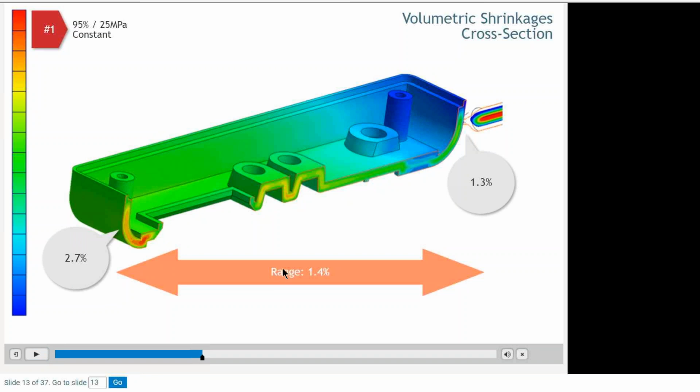That's very important to understand in injection molding and for the processors. So how do we know what volumetric shrinkage we have? Well, you don't really know what volumetric shrinkage you have, but you will know what it does to the dimensions. So as usual in injection molding, the areas further away from the gate get less pressurized. If it gets less pressurized, it has higher shrinkages, so volumetric shrinkage goes up. Near the gate, because the pressure comes through the gate, we have less volumetric shrinkage.